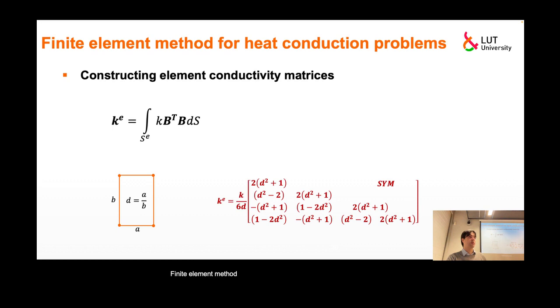The numerical integration that you studied with Grzegorz two weeks before is used in real finite element analysis to calculate those integrals, those properties related to elements. It might be element conductivity in our example, or the element stiffness matrix in case of elasticity, for instance, or something else if you are dealing with different types of problems. In our case, I can calculate it analytically, because I'm using very simple elements, but in the general case, it's calculated numerically, and those numerical methods that you considered can be used here, and they are used.